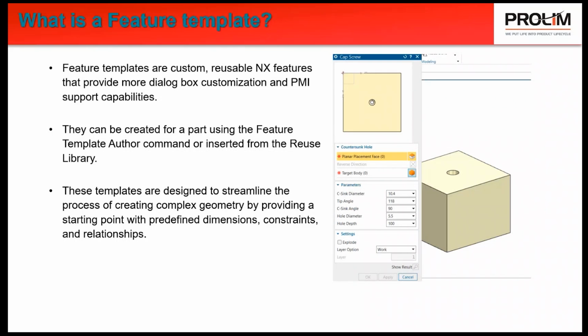Feature templates in NX are predefined sets of parameters and specifications which allow users to design complex geometries more efficiently. These templates can be used for creating common features such as holes, pockets, fillets, chamfers, and even some more complex geometries. So let's take a look at this.